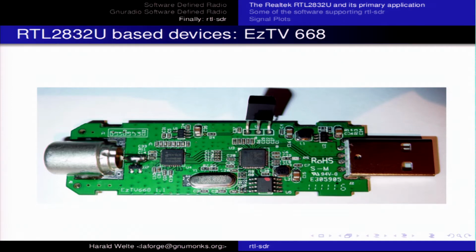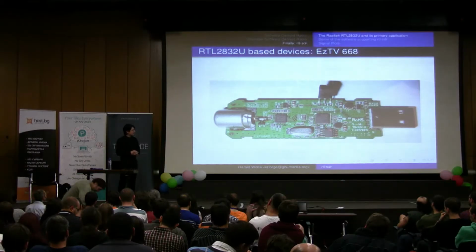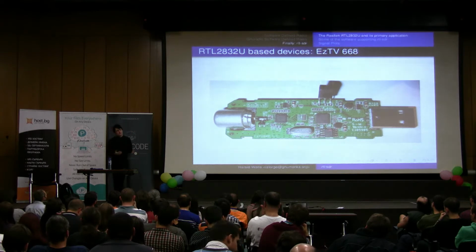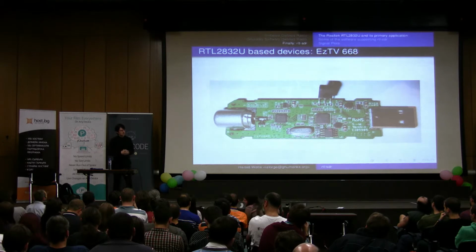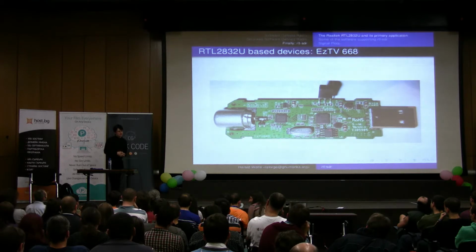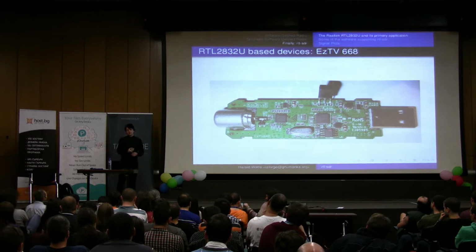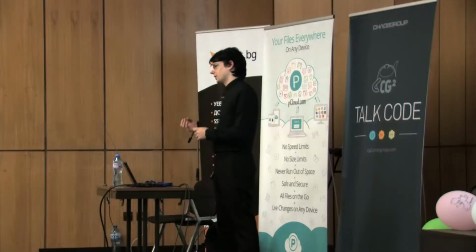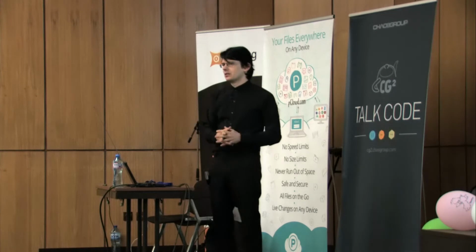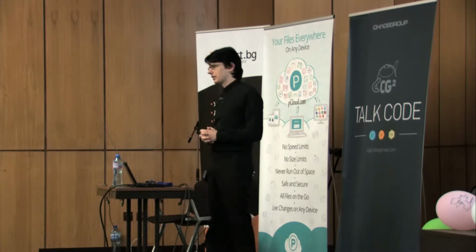So basically, if you put those things together, the open source software and one of these cheap receivers, you have a very powerful radio receiver, and you can use any of the SDR software that is commonly available in open source, particularly anything that's based around the GNU Radio framework, because rtl-sdr integrates as a so-called source. So you can take samples out of the receiver, feed them into GNU Radio, and then do whatever receivers are there.